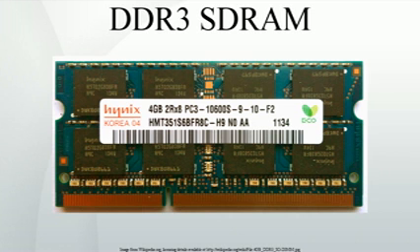Overview. Compared to DDR2 memory, DDR3 memory uses 30% less power. This reduction comes from the difference in supply voltages, 1.8 V or 2.5 V for DDR2, and 1.5 V for DDR3. The 1.5 V supply voltage works well with the 90-nanometer fabrication technology used in the original DDR3 chips. Some manufacturers further propose using dual-gate transistors to reduce leakage of current.